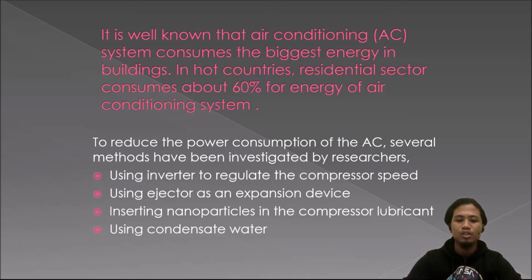First, using an inverter to regulate the compressor speed. Second, using an injector as an expansion device. Third, inserting nanoparticles in the compressor lubricant. And lastly, using condensate water.